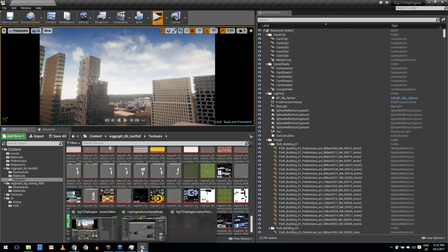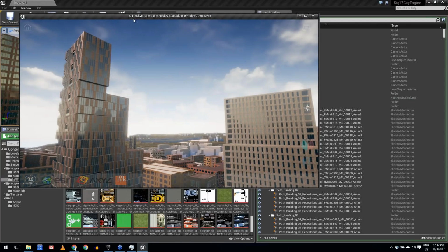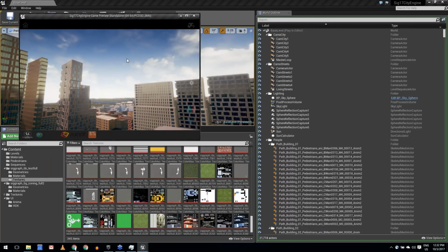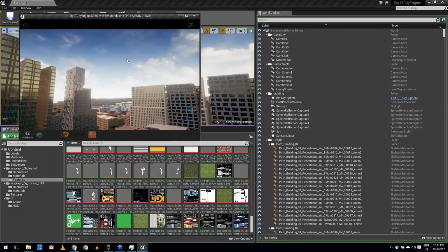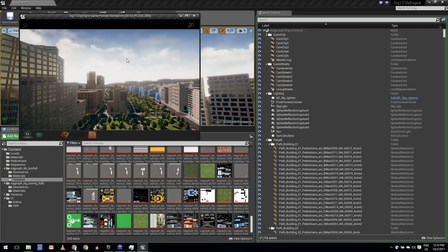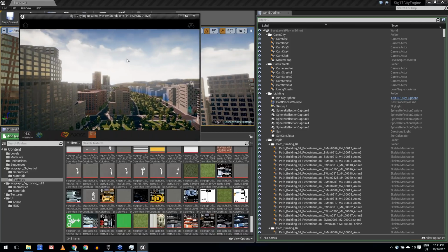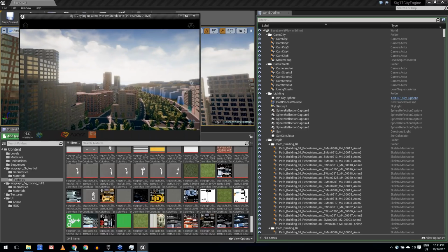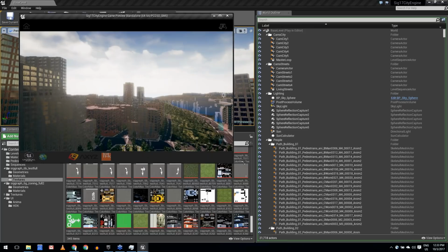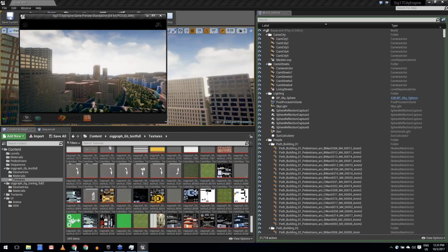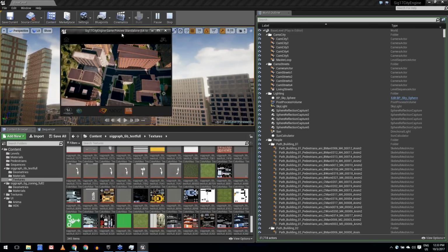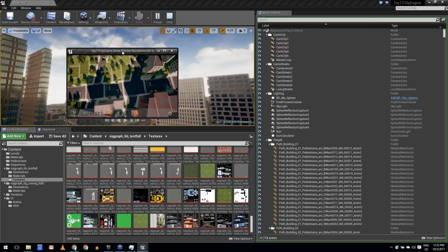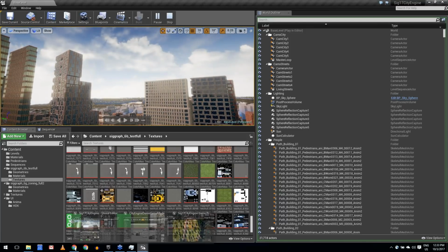It was during your presentation. Trip was asking, were you able to extract the building footprints, the heights, and the roads from the base map and the elevation layer? So the building footprints and the roads are actually coming from the OpenStreetMap servers. So we don't do any feature extraction at this stage. We basically use what the OpenStreetMap community has ingested into their database, and we have a bunch of built-in rules inside CityEngine which understand the OpenStreetMap annotations or attribute data. We try to interpret those. So, for example, they have something like a number of floors, and we assume a standard floor height and extrapolate the building height from that. I hope that answers this question.